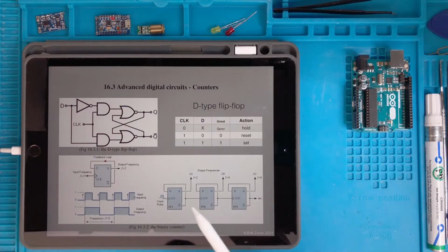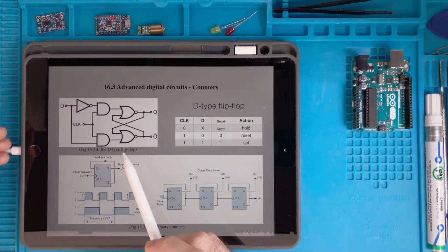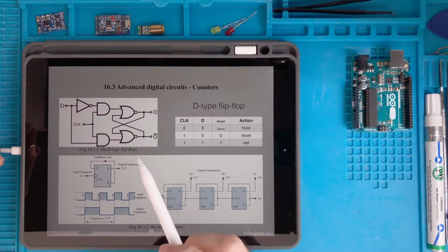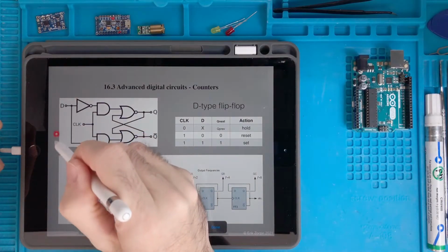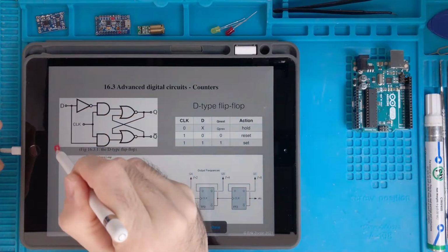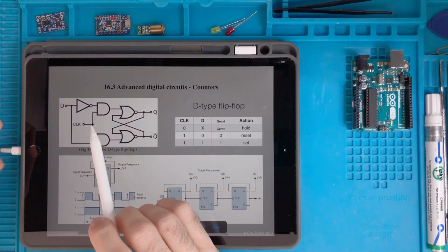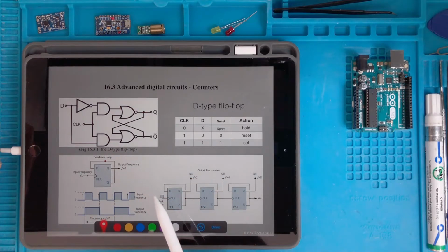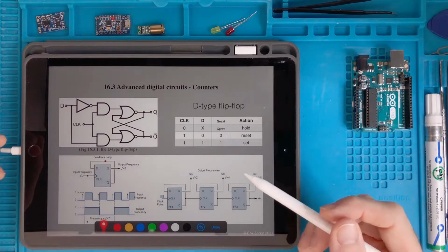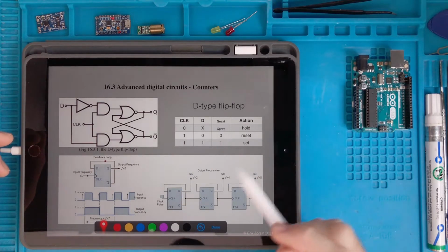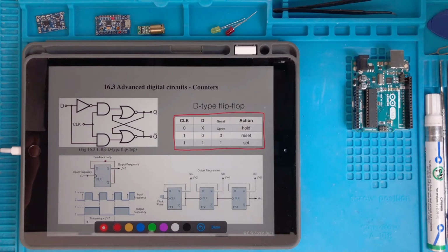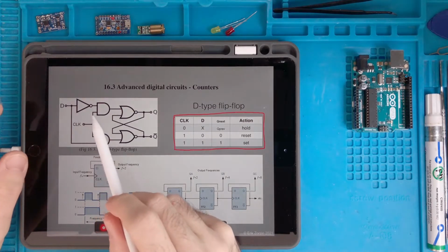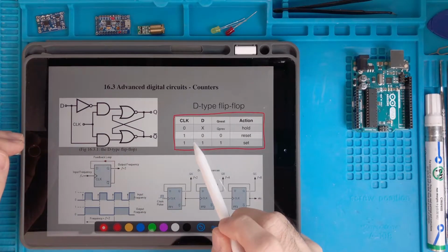So now, in order to improve this flip-flop latch, also called the set reset flip-flop, we have this circuit which is called the D-type latch or the D-type flip-flop, which has a little bit of circuitry before this that we already analyzed, and this will remove that unwanted condition of the forbidden case, producing, to make a long story short, this truth table. So if we are careful and we analyze this thing step by step, we will arrive at this result.